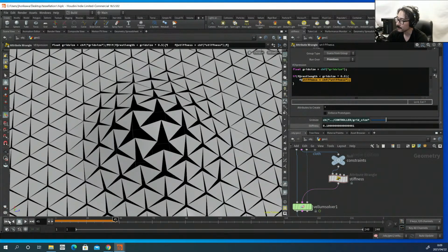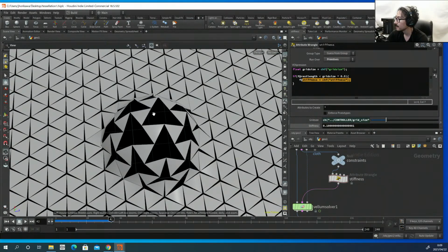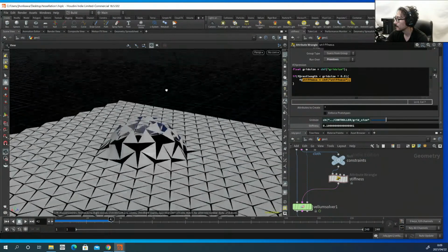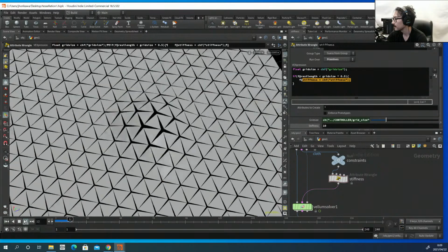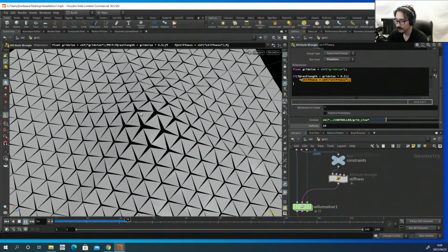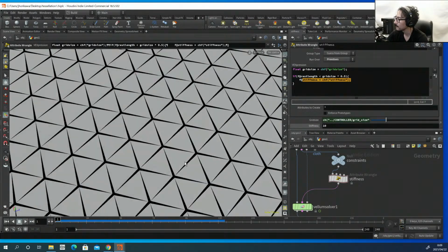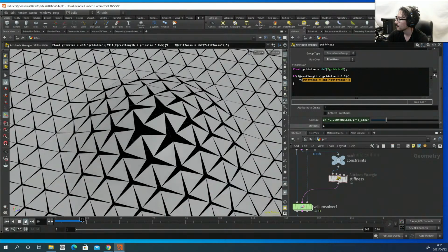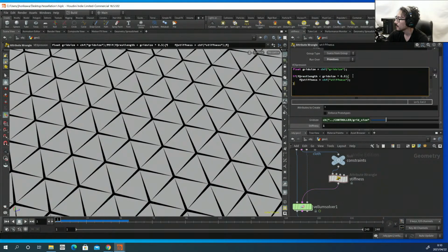If I make it 0.01, maybe that's too much. Maybe that's not constrained anymore, in my opinion. How about 10? I make it 10. Now you see little smaller holes start to appear. So what I would love, maybe somewhere around 1 is the one that I really like. Okay, it's good.